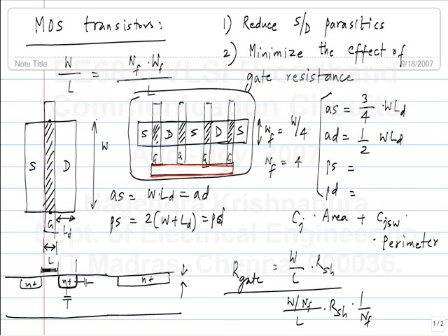So, you are talking about the resistance of this part. So, firstly, this doesn't have to be poly, this can be metal, right. Once you use metal, the resistance of metal is so much lower than poly that you don't have to account for it. So, this can be a bar of metal, and then you have contacts here.